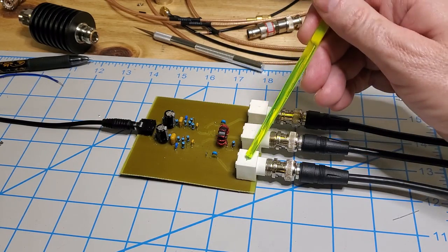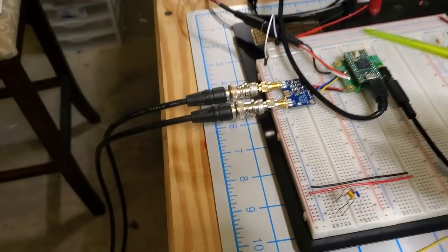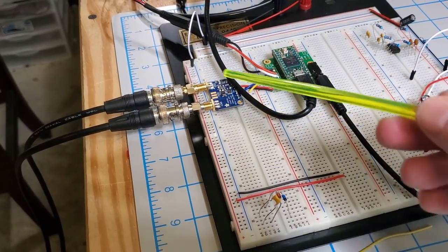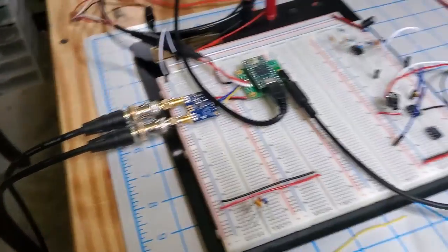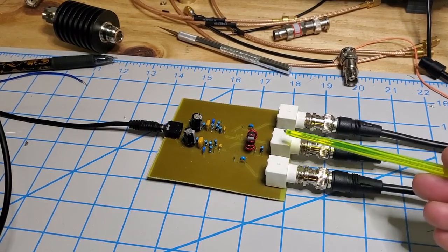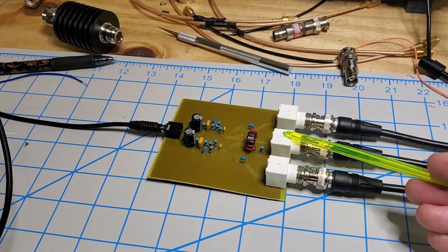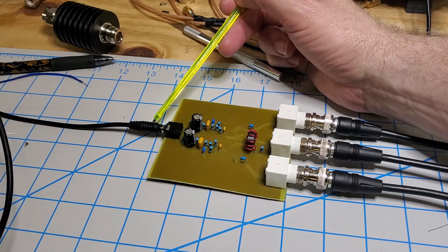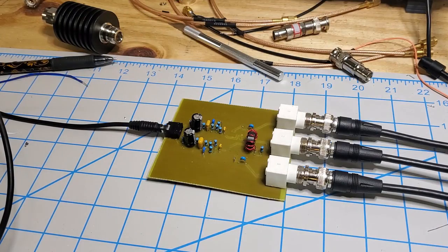So these two channels here are the LO signals that are coming from the SI5351 at 90 degrees out of phase with one another. So that's just controlled by the Teensy, and I've just got that hard-coded to 7 megahertz for the moment. So they're going into here and here, the LO signals. This is where I'm tapping the output, and that's going off to the signal analyzer. And then this stereo signal here, the left channel contains the 0 degrees and the right channel contains the 90 degrees signal from the Teensy.